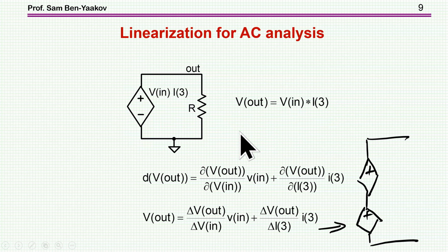So what has to be done is to linearize it. LTspice, as well as many other simulators which are based on the original SPICE or some other engine, do have the capability of doing this linearization. This is done automatically, transparent to the user, and it entails taking the differential, that is the partial derivative of the function, with respect to each of the variables.